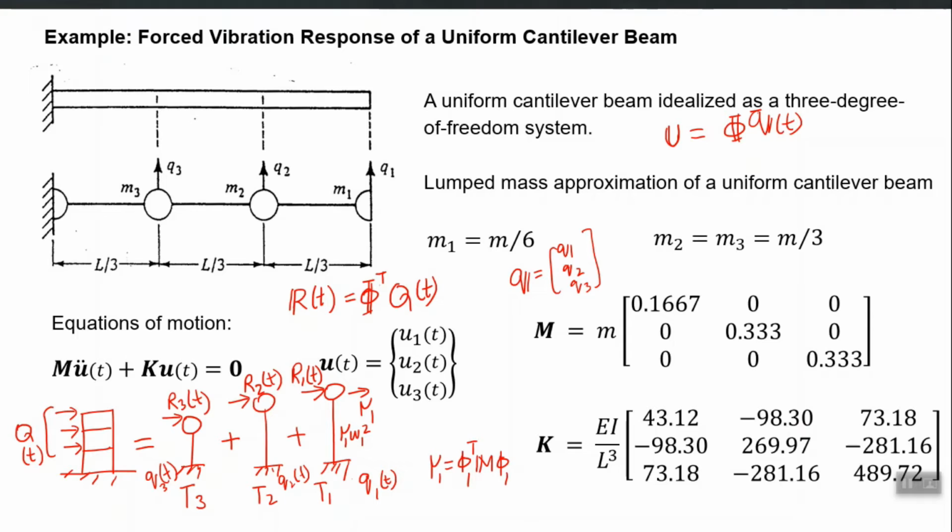So you apply the same earthquake to those 3 modal SDF systems and sum their responses, and you get the same response as when you apply the earthquake to the very detailed mathematical model, the complete detailed multiple degree of freedom system. So it means in commercial programs also, if you set the analysis option to modal RHA, it should take significantly less analysis time compared to direct integration, for example, right.